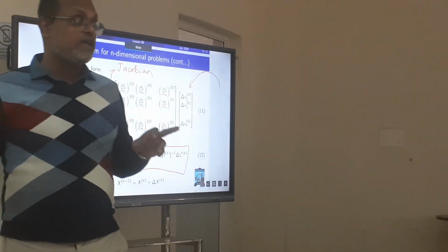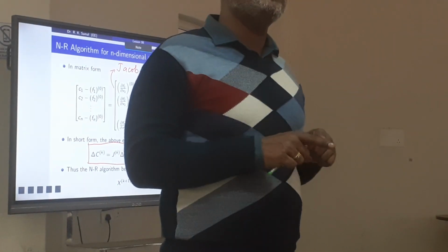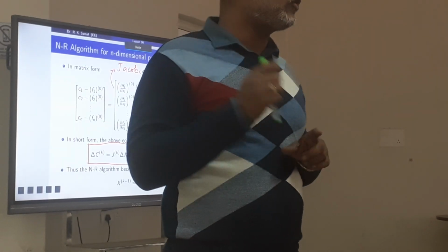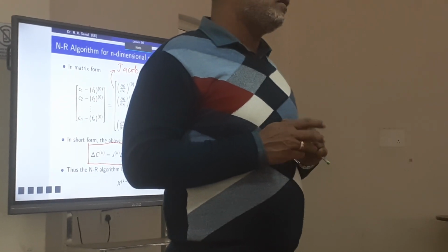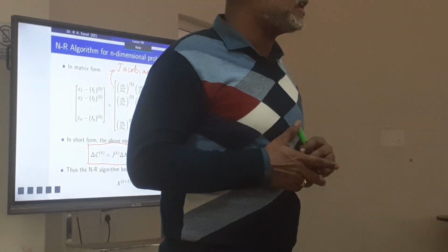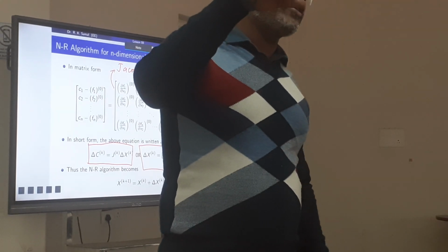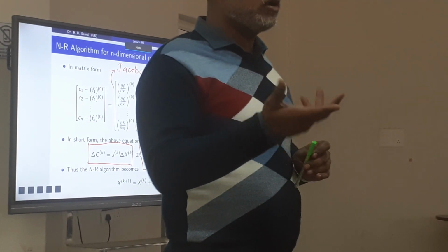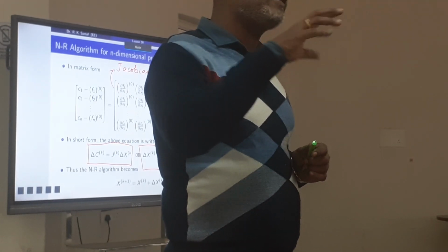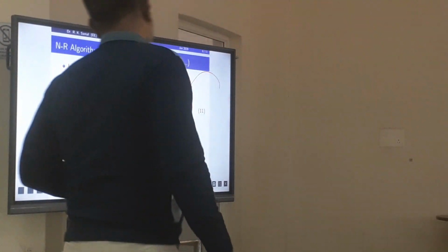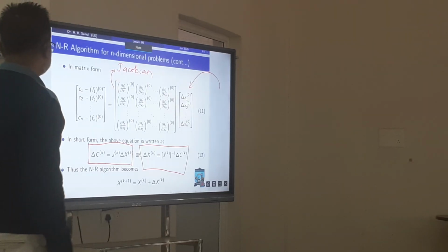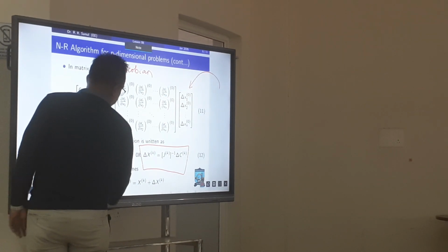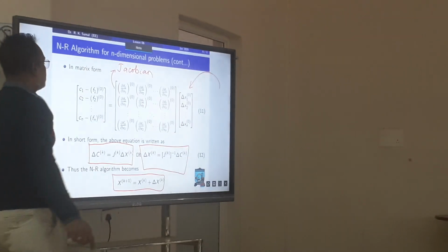That means in our case, when we solve the power flow equation, we have to form the Jacobian and take an inverse of that. That's why the Newton-Raphson method is computationally very demanding, because we take matrix inversion. Suppose it's a 100 bus system, then a 100 cross 100 matrix inversion. Okay, and you have got the MATPOWER software. It's open source code, so you can go through the source and see how these inversions are taking place. They use a method known as sparse matrix computations, okay, to make it faster. And finally you take the increment up to get the final value.